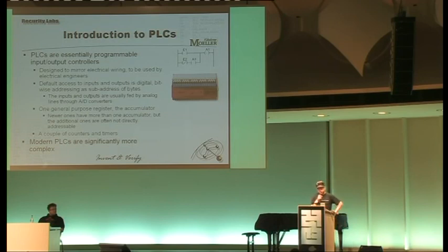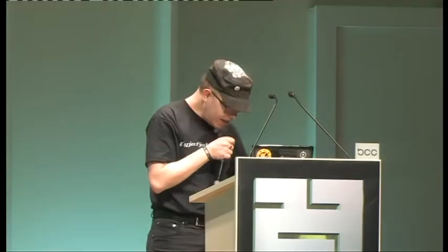By default, you have digital inputs and outputs that you can program, and there are some analog digital converters connected to them, and then you can drive motors or pumps or whatever. From a programming perspective, it's a one register machine. It usually has only one register, an accumulator. Newer ones have more than one accumulator register, but you can't address them directly.